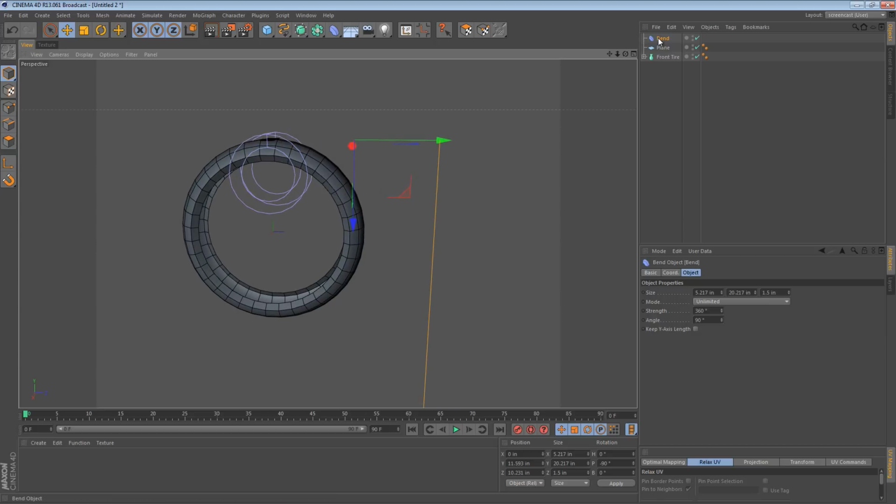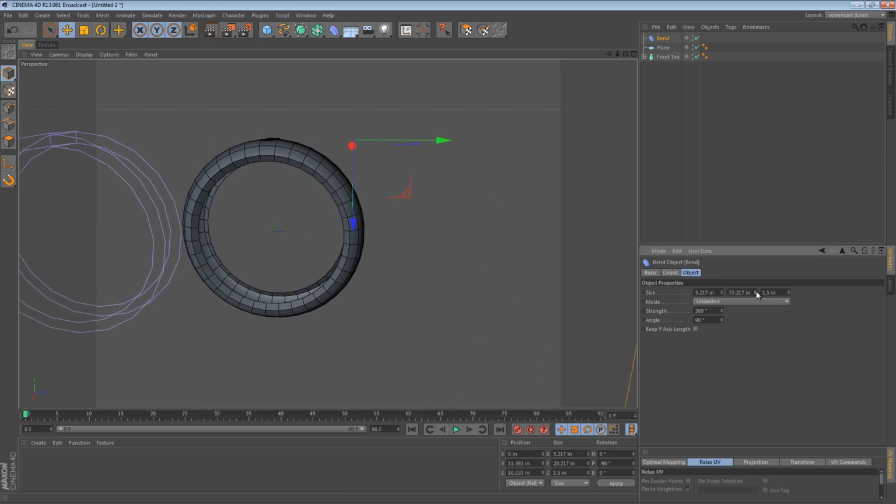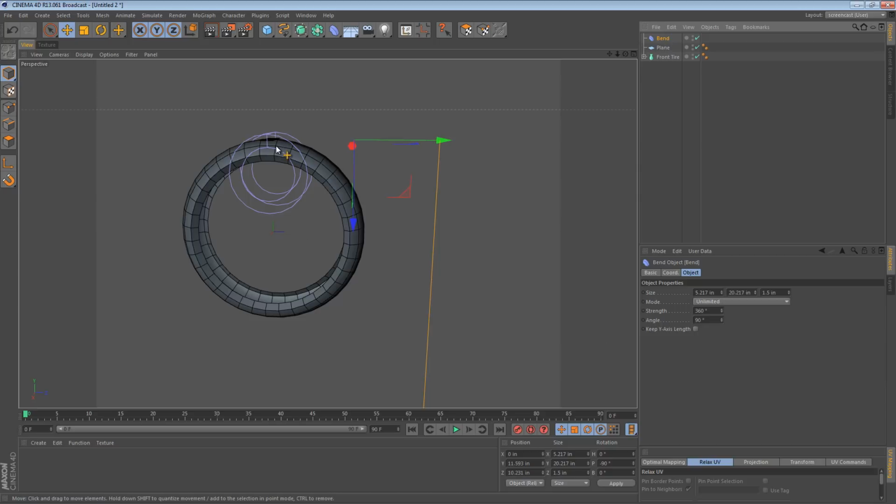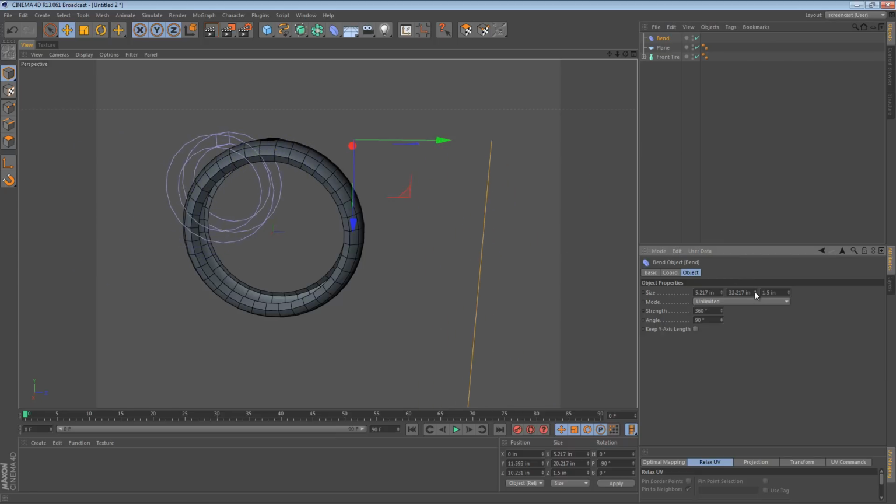The next thing we need to figure out is how long is that circle, how long does it need to be to fit our tire perfectly? To figure that out, we can apply pi to the diameter of this circle. So we know the radius of the circle, 11.593, from the center to the edge. So the diameter is 11.593 times 2. And if my math doesn't fail me, I believe the circumference, in other words, the y length, should be 11.593 times 2 times pi. So let's see what that gives us. I hope I'm right here.